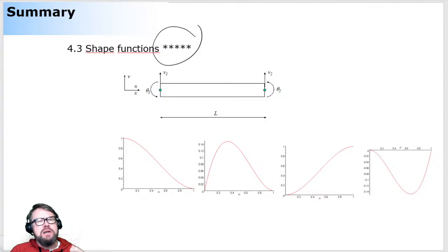So what is the physical interpretation of shape functions? How can you get the shape functions? And again, it's coming from the polynomials. They are telling you that if I'm introducing the unit displacement to 1 degree of freedom in my element, how are the particles between the nodes expected to follow that displacement?